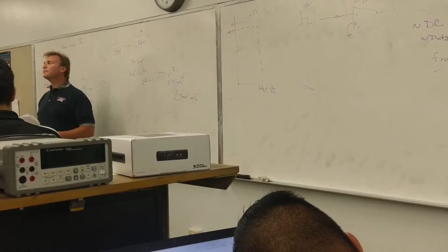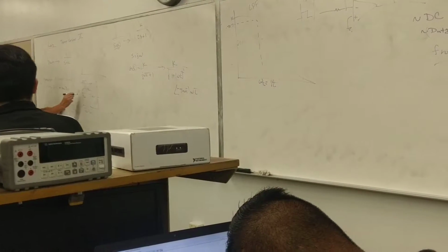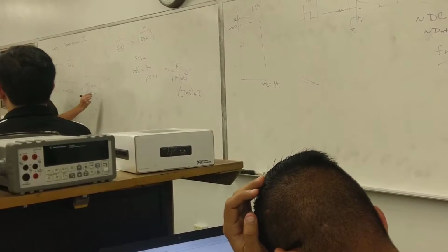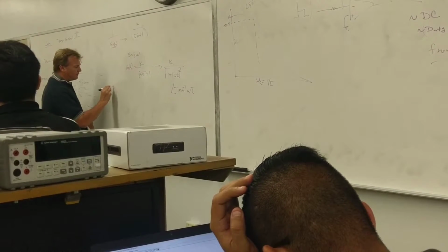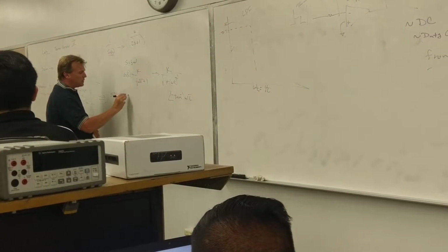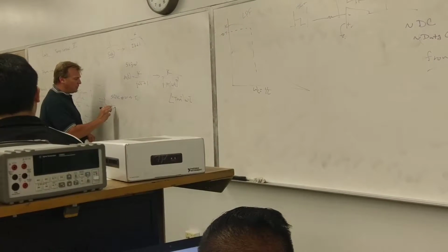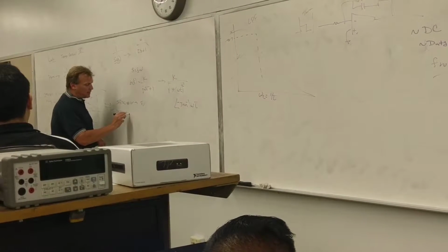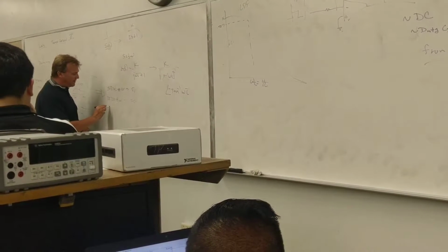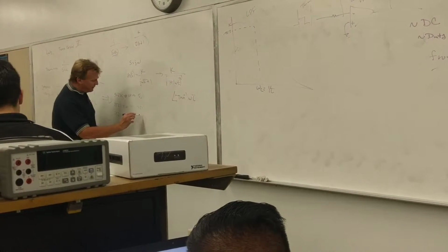So far so good? So the way this works, if I have some V, let's just suppose this is equal to 10 volts, with a percent duty cycle of 50%. At 10 volts, that is obviously going to produce 5 volts, right? And a 25% duty cycle at 10 volts is going to produce 2.5 volts. A 75% duty cycle at 10 volts is obviously 7.5.